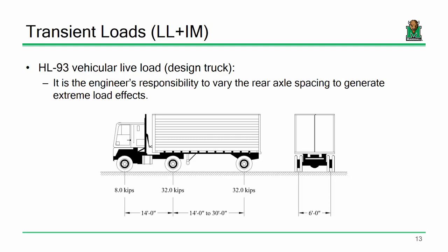I got a pop quiz for you. All right. Remember how I said HS20, the HS20? If this axle weighs 8 kips, how much does each wheel weigh? What about here? What's 4 plus 16? That's where that comes from. No. This axle is 32 kips. Now, that's just off the image. We're saying 2 wheel lines. So I see what you're saying.